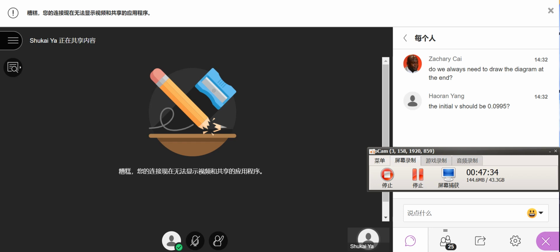Because this is the damping ratio, it's very hard for us to test the damping ratio of a structure. It's not a parameter that you can obtain directly. But if we do some experiment, it's very easy to measure the displacement. Then if we get the values for ui and ui plus j, reversely, we can derive the damping ratio, and then we get everything like C and Ccr.